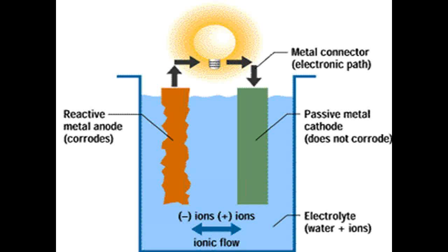It would be broken when you took that light bulb out of it. Same thing in this battery. If you allowed the battery acid to get down below the plates so it didn't make contact with both plates, that light bulb would go off. You'd break the circuit because we didn't have the electrolyte. So you've got to have all 4 components to get this activity to occur. It corrodes the anodes here. It comes down through here, carries back down through here. A battery is just an electrical circuit, and corrosion is just an electrical circuit.